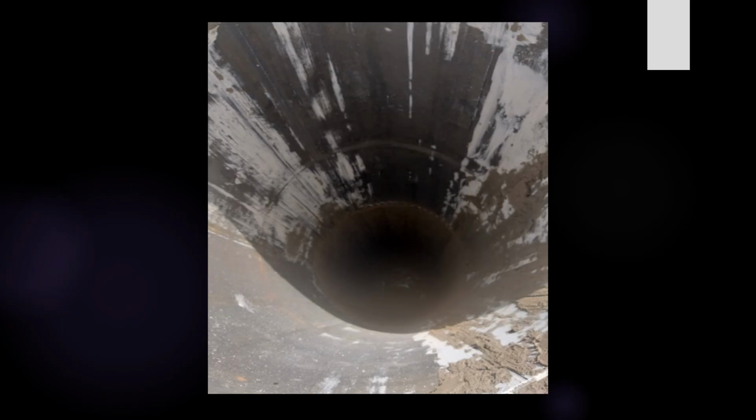This is the casing, as we have previously discussed. This is the casing that we are going to insert for what? For general excavation, because the soil may collapse or cave in. So to protect the topsoil from the overburden pressure, we need a casing to support the horizontal load from the surrounding soil up to only 3 meters. Afterwards, we have other mechanisms.